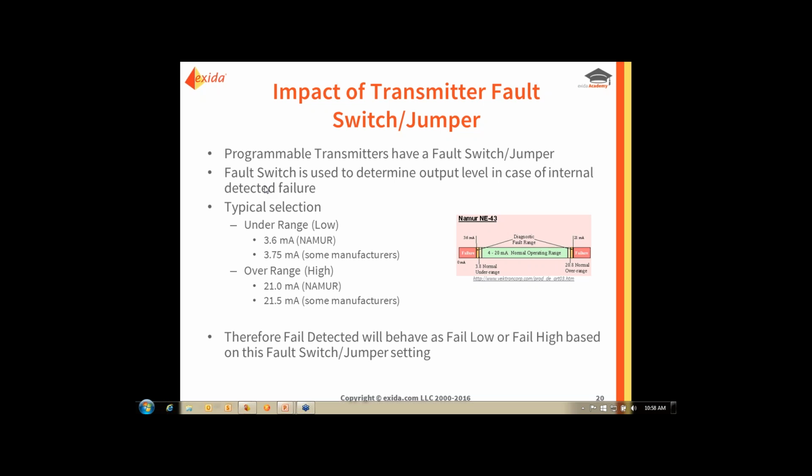So, for example, if you need to do any measurement with regard to gas flow, and you're using that to control the amount of gas that goes into a furnace and prevent overheating, then it becomes a whole lot more important than if you say, hey, on average I have an output in the 20 milliamp range. If it goes above 60 milliamps, I need to go to the safe state, but it hardly ever comes close to 60 milliamps under normal operating conditions.